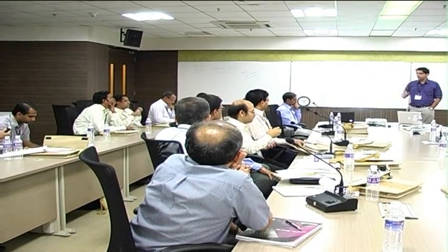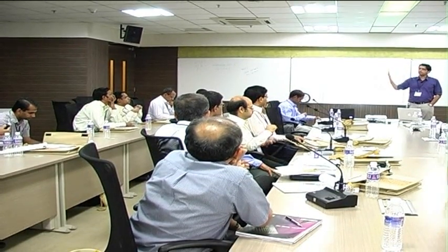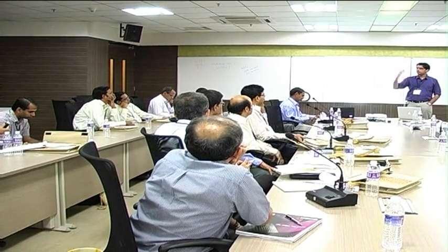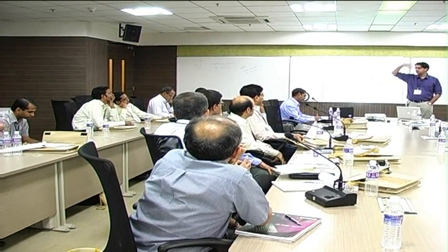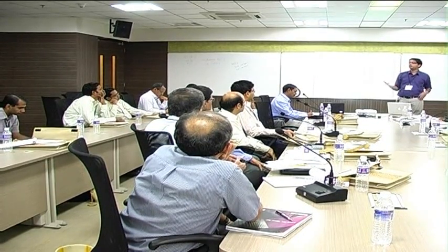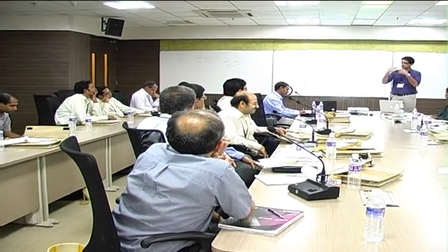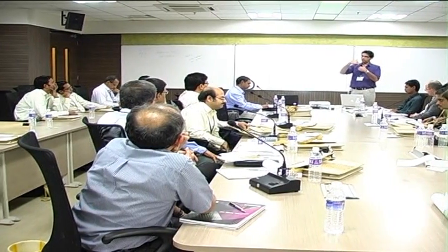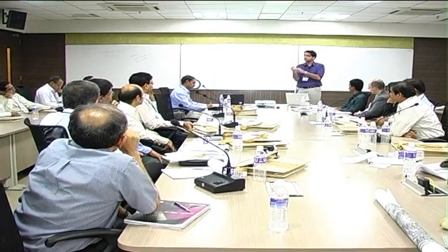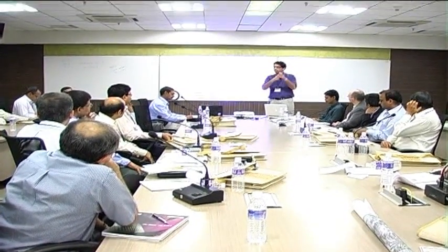So as long as you don't hit frequencies that are so high that you start hitting some Karlovitz number of one of the internal reaction zone reactions, you should be okay. Essentially, your external forcing is of a sufficiently slow time scale such that the reaction zone can instantaneously adjust to whatever happens. So you can say that SL equals SL of local phi, quasi-steady.